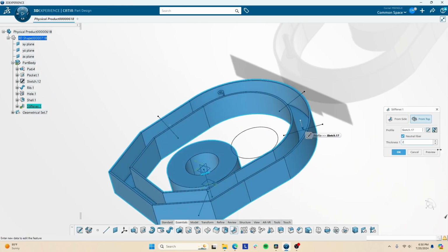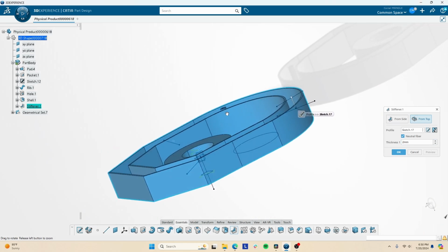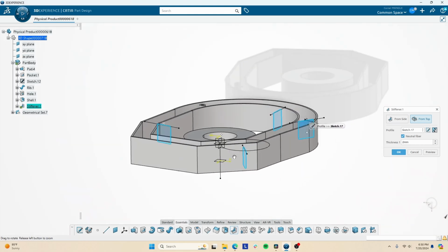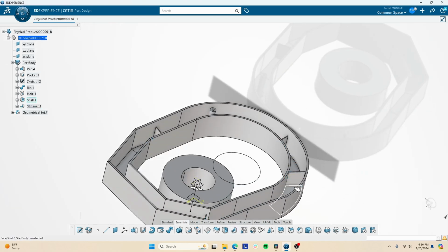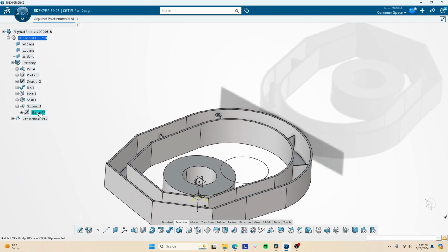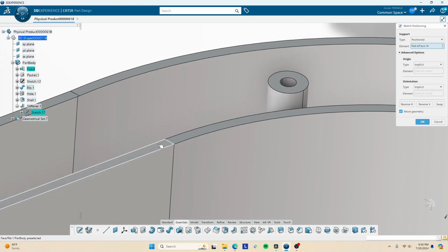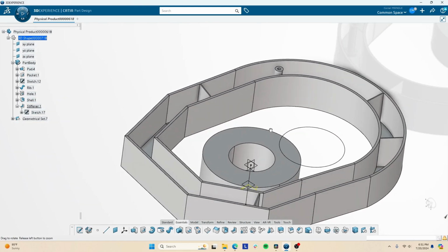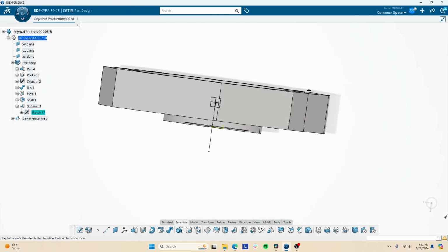Let's make it like 2 millimeters, preview. Oh, there you go. The direction. I sort of meant to do it on that top face, but that's all right. It's one opportunity to show you another feature anyways. Let's change sketch support. I could change it to, again, it's not good practice to do it on these faces, I'm just doing it for this tutorial. Once I do it on that top face, you see the stiffeners come up all the way to the top because I changed the plane on which the sketch was based on to begin with.